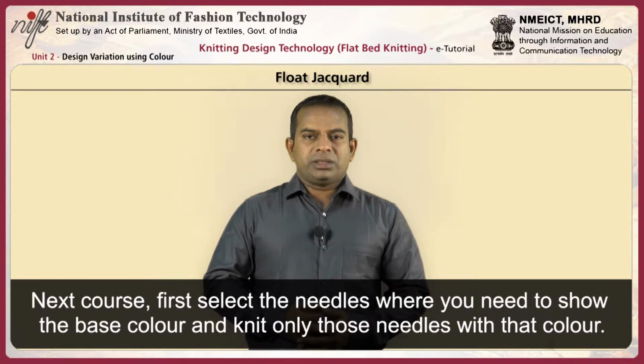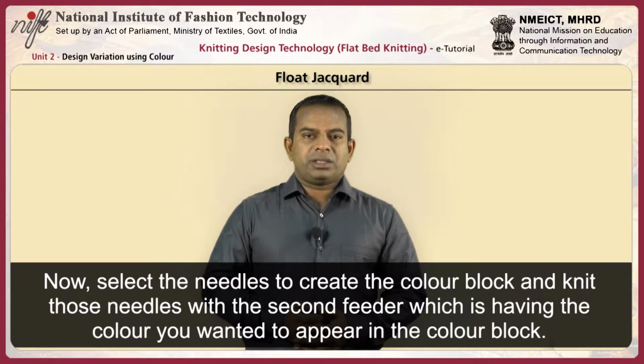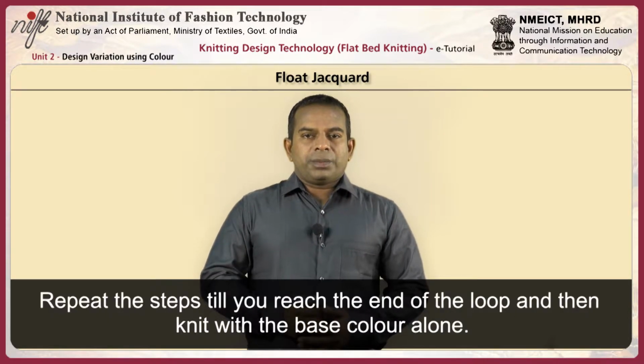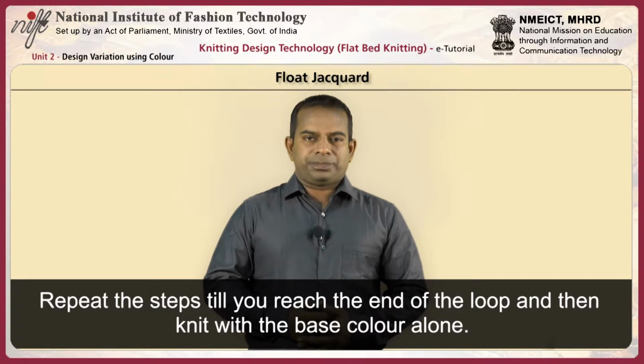Next course, first select the needles where you need to show the base color and knit only those needles with that color. Now select the needles to create the color block and knit those needles with the second feeder, which has the color you want to appear in the color block. Repeat the step till you reach the end of the block and then knit with the base color alone.